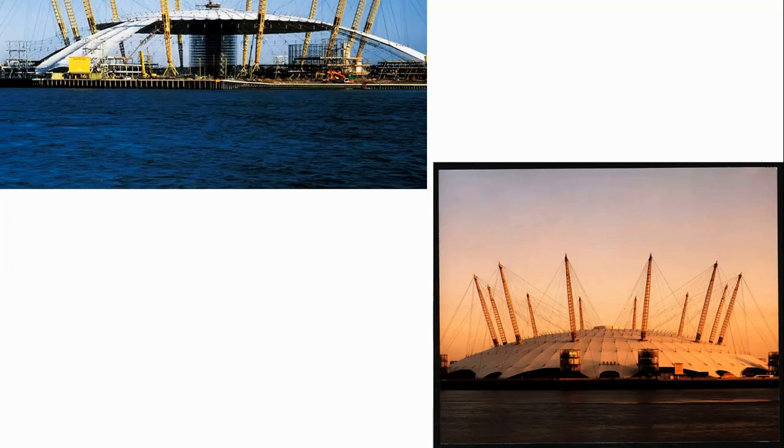And you know this one, you're probably familiar with it. You call it the O2 Arena. As I said, I always thought it never got better than that. It looked like a sort of cloud when it was being built. It was a very interesting, very beautiful structure. But as I say, this is the cable-stayed structure rotated. So in another world, it would be a series of bridges, 6 bridges, wouldn't it, rotated around the center point. Each one of the masts has an equal and opposite on the other side and is pulled back down to ground, remember, with some mass that's counterbalancing the structure.